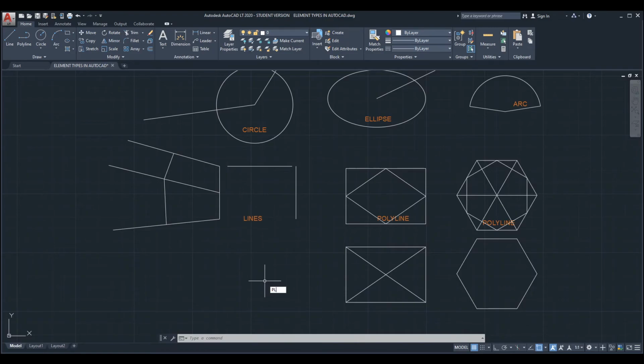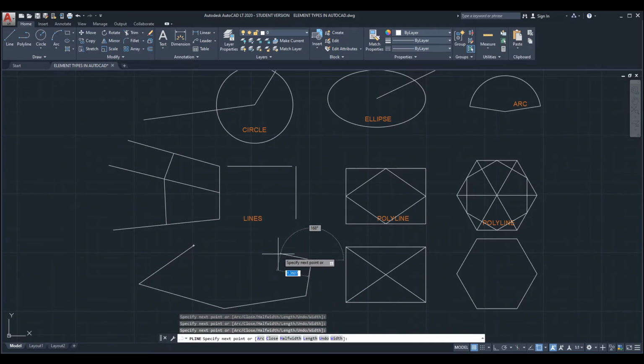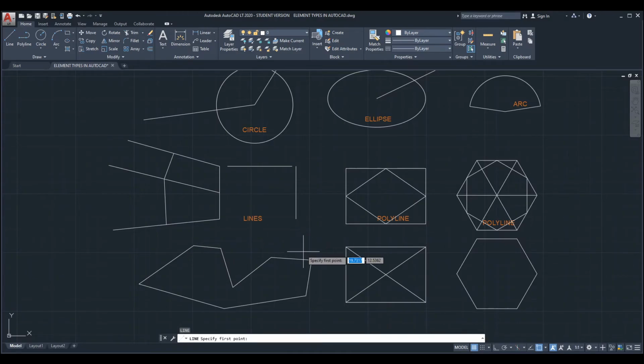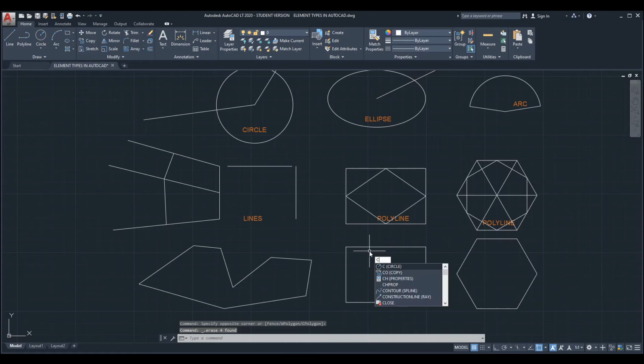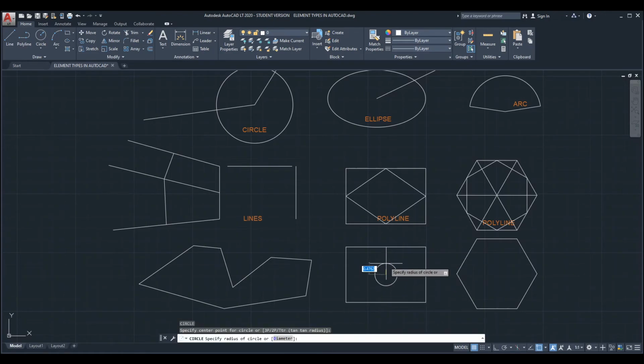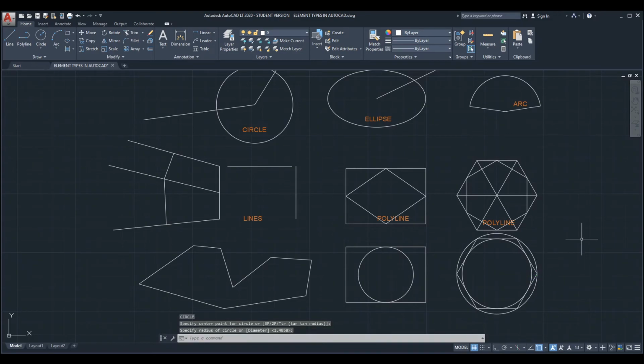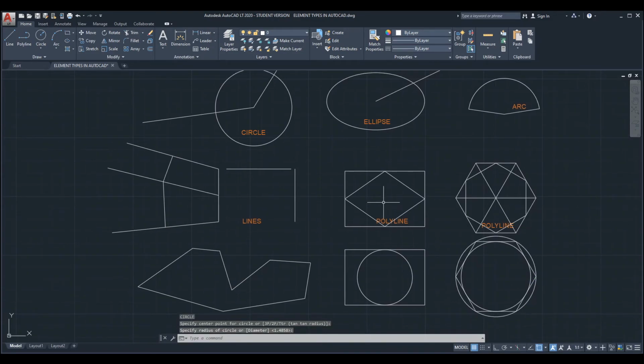So if I make a polyline right now with an odd shape, something like this, for example, this geometry also has a center, and if you just touch the perimeter, this point right here represents the center of this geometry. AutoCAD calculates and figures it out, and it will show it to you. But usually I use it for finding the center of a rectangle. For example, here, if I want to draw a circle in the center of this rectangle, then I can find the point, and then I can do something like this. And the same with this one, I can draw like this, and another one maybe to the outside, and we get a shape like this.